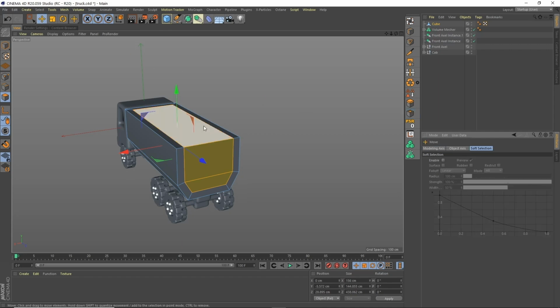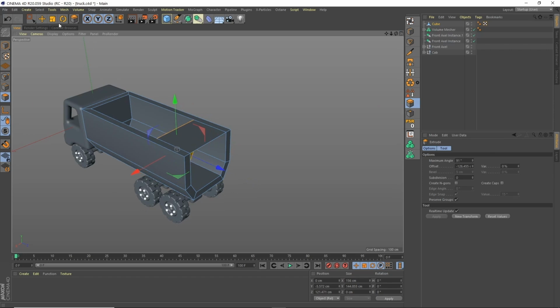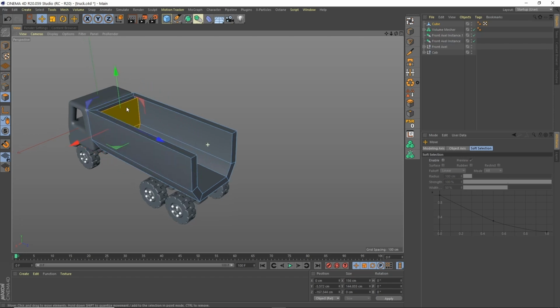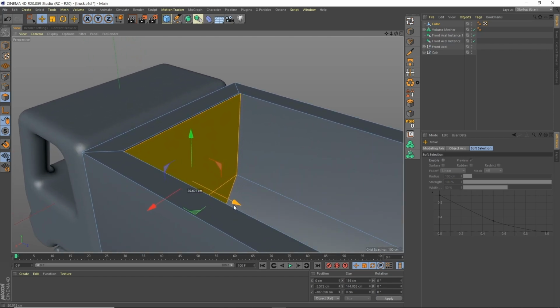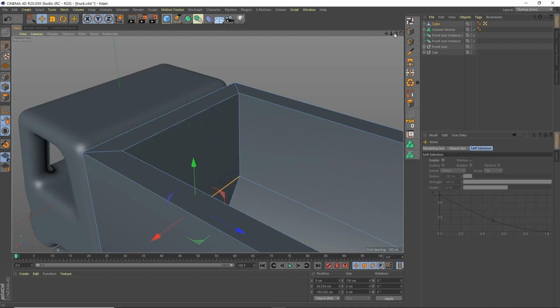What I'm going to do is delete this top section and grab these 2, and I'm just going to extrude these out. Extrude it a bit. I'll delete the top. Those 2 selected. I'm going to push these all the way back, and then I want it obviously to join up. So grab these and maybe do stitch. That's the stitch and sew tool.